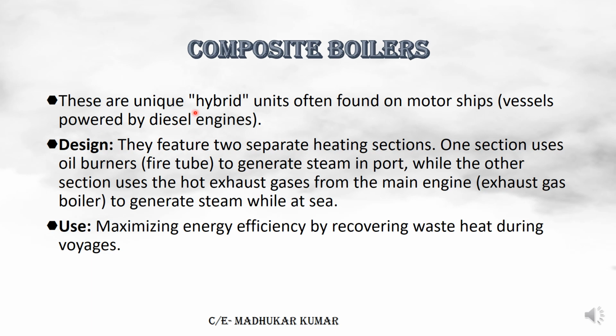Composite boiler. This is the most widely used, basically you will see on bulk carriers and all. This has a hybrid construction, found on motor ships where we have the main engine. So main engine exhaust we can use, and as input we can also use the burner. So steam generation is possible for port and for sailing time also.